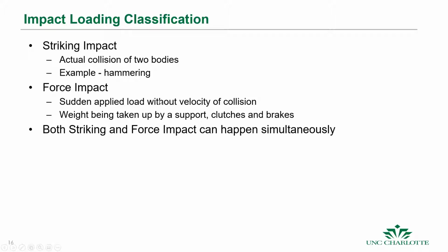All right. So there are different classifications of impact loading. Striking impact is when we actually have a collision of two bodies, such as hammering. Force impact is different. It's when you have a sudden applied load without the velocity of collision. You can think of it as like a weight being taken up by a support, or the application of a clutch or brake, or disengaging and engaging.